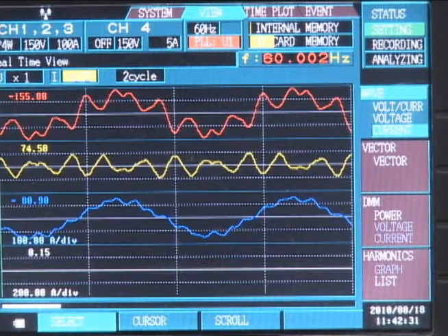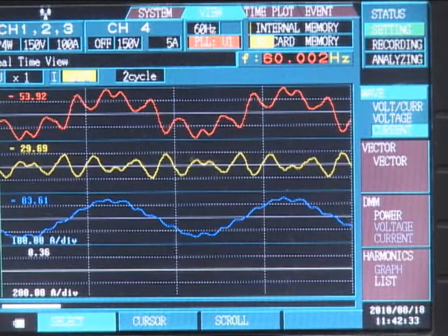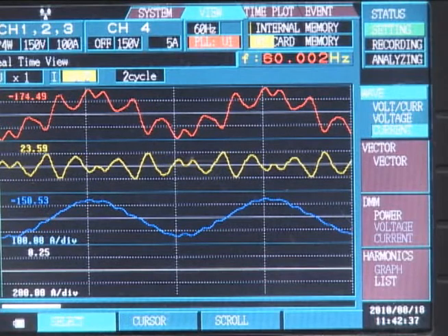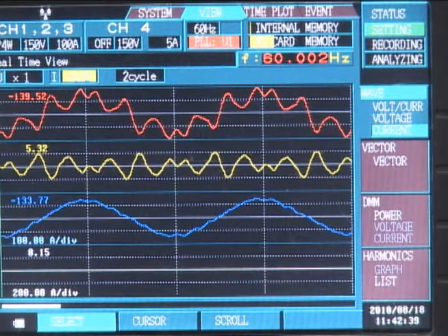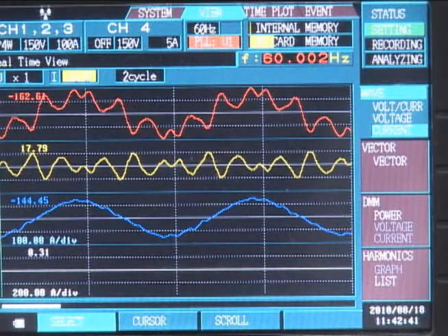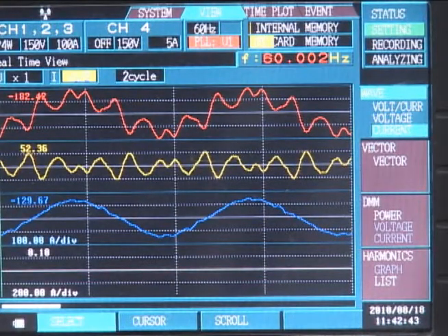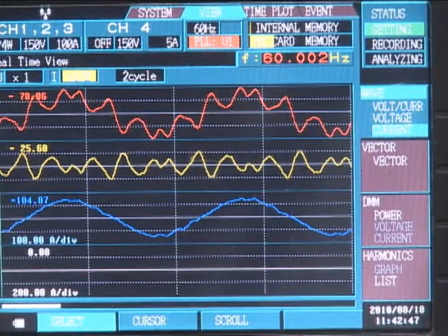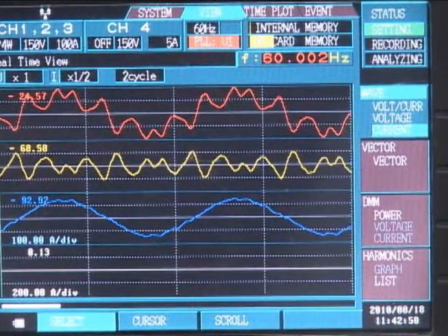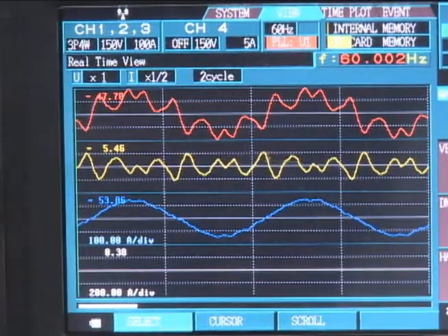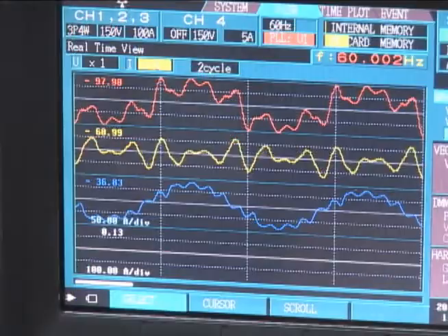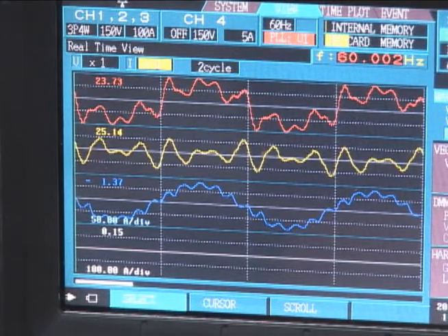The 5th harmonic is now selected. The active filter will only filter that harmonic component, as the filtering target is set to 0. The filter will take out the entire 5th harmonic generated by the load. The spectral analysis clearly indicates the 5th harmonic has disappeared from the line current waveform. The filter current is a sine wave with a frequency 5 times the fundamental frequency, and the resulting line current is a cleaner sine wave.